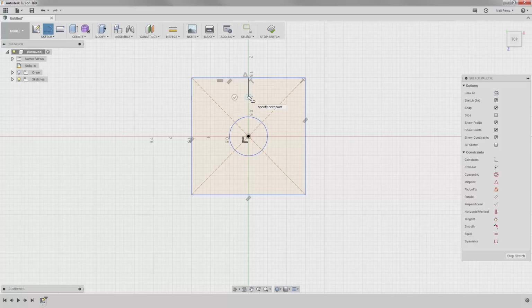We'll left click, and notice that once we place that, we have a green check mark that's located next to the coordinate point. This allows us to end the line tool. But in our case, what we want to do is drag the line to the right until it intersects the upper construction line. We want to make sure that this line is horizontal, and then we want to hover over the last point, hold down the left mouse button, and drag away. Notice that this places an arc on here instead of just a line. Next, let's hit Escape on the keyboard.